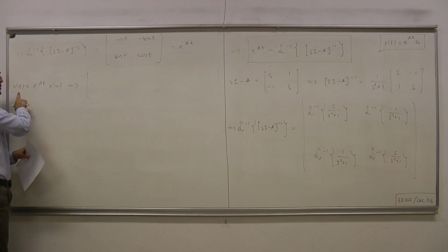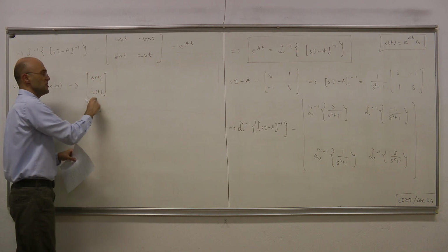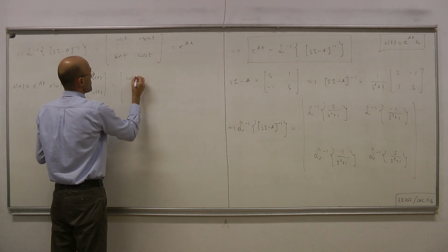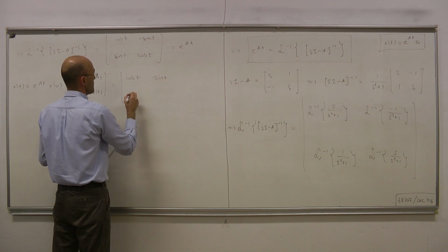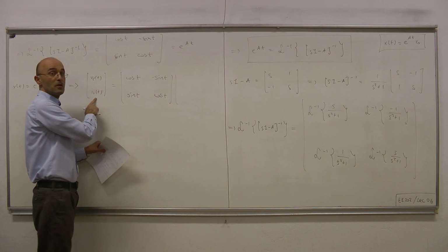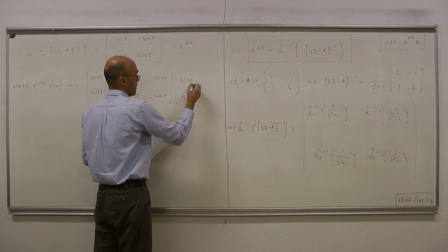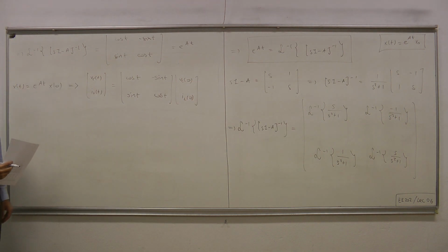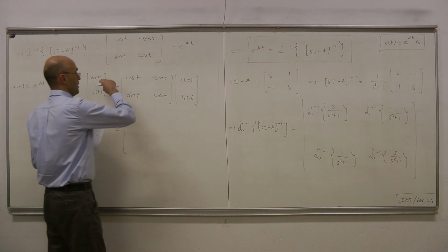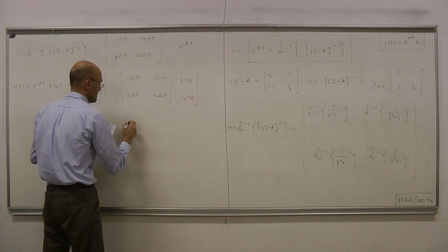So what was our state? Our state was VC and IL. Okay, so VC(t) and IL(t) must equal, therefore, the matrix cosine t, minus sine t, cosine t times the initial state, by which we mean initial capacitor voltage and initial inductor current. Then, if you perform this multiplication, for the first entry you have cosine t times VC0 minus IL0 times sine t.